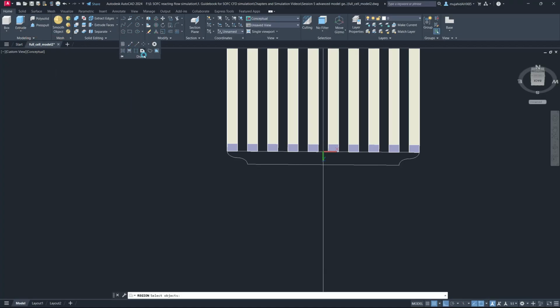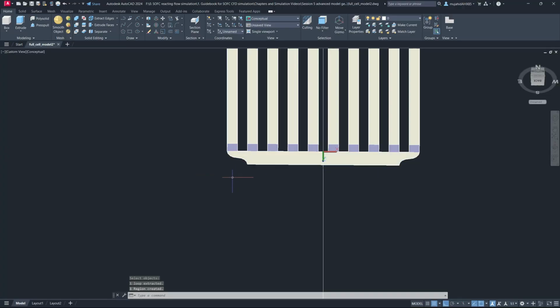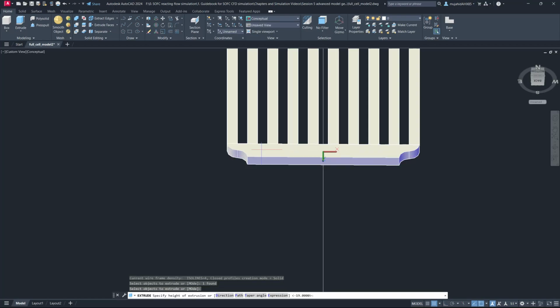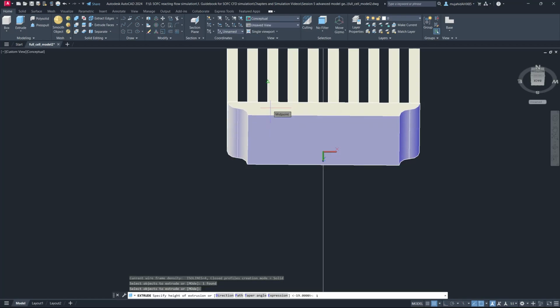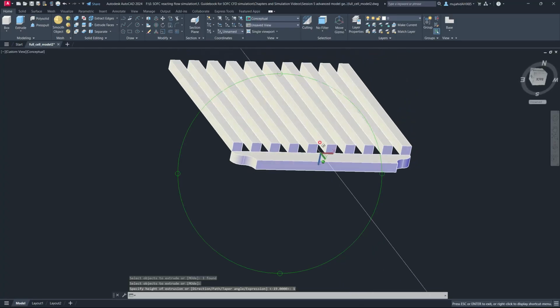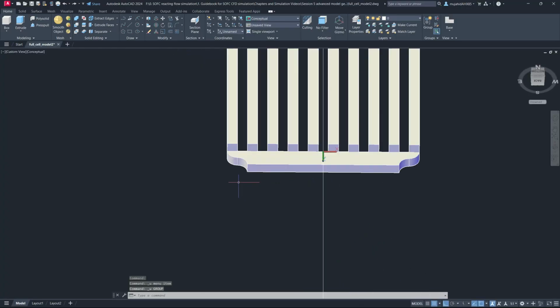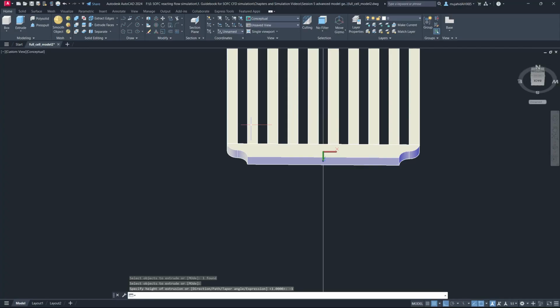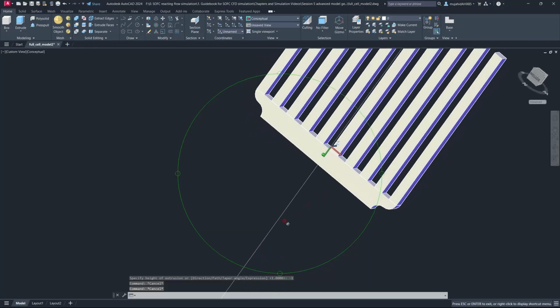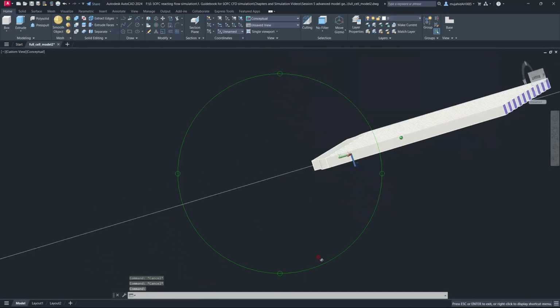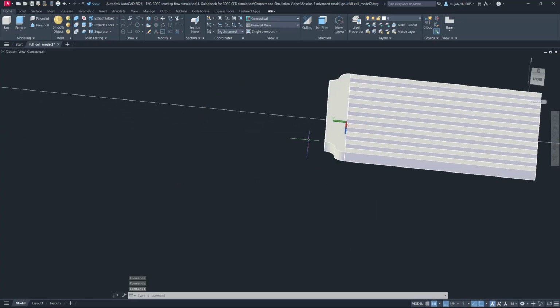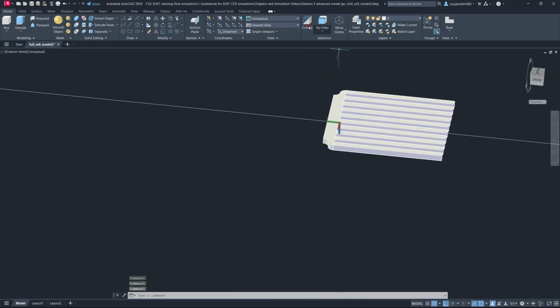You can make a region, this is the command for region, and select all the lines. So now the region is created, so we can extrude it now in 1 mm. The 1 mm is in the opposite direction, so Control Z, extrude it -1. Okay, now we can mirror the whole 3D object also, so we'll use the mirror command and move our coordinate system.